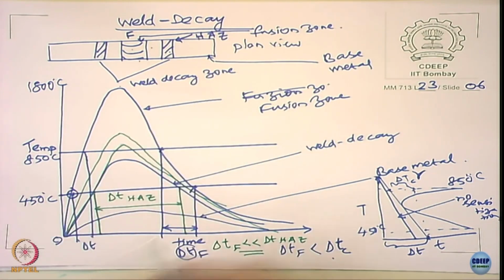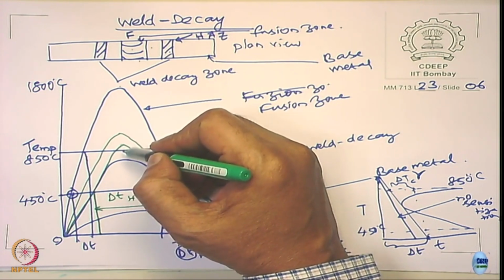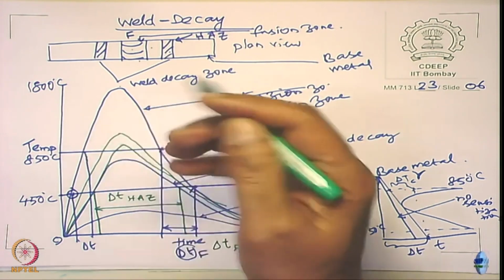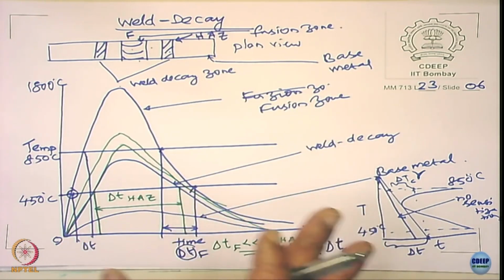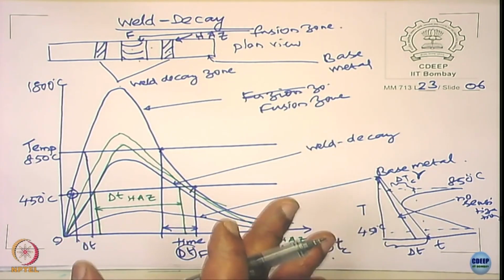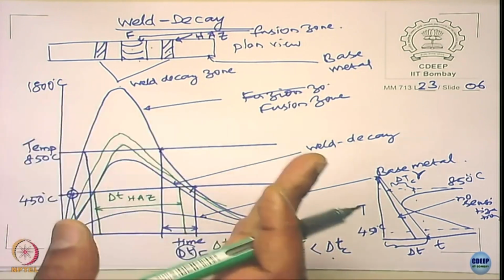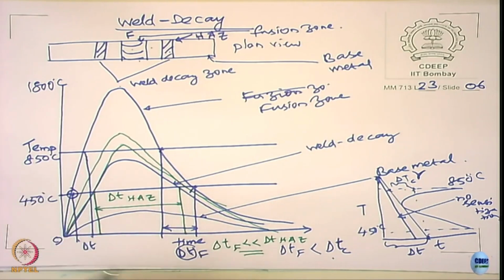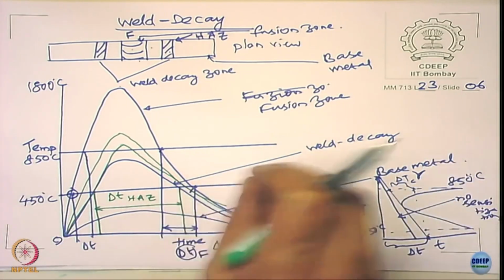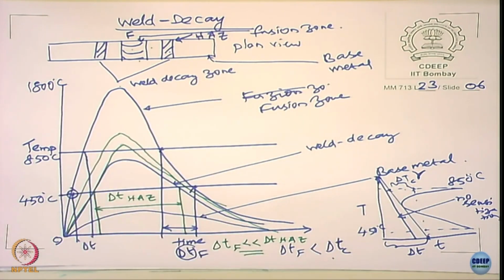Okay. So what we are assuming here is that when it goes up, the chromium carbide dissolves. Actually, dissolution of carbides is much easier than nucleation. If you look at it generally, dissolving is much easier. Normally overheating is not required when you melt it. When you cool it down, you need an undercooling because nucleation and growth is a problem. But apart from that, you can calculate and see what really happens in the thermal cycles actually.